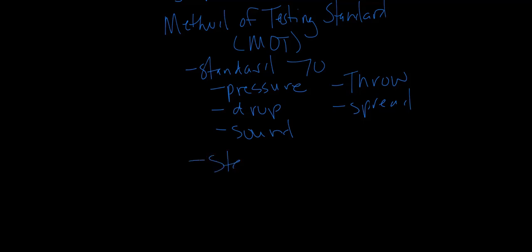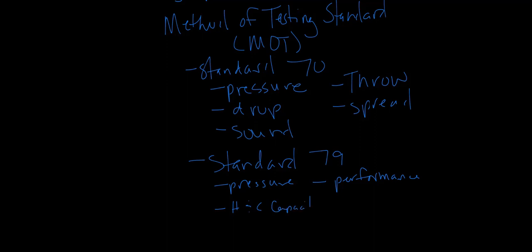Then we have Standard 79, which describes the method of testing for fan coil units. This standard is open for revision currently. This standard will test for pressure across the coils, for coil performance, heating and cooling capacities, and sound generation.